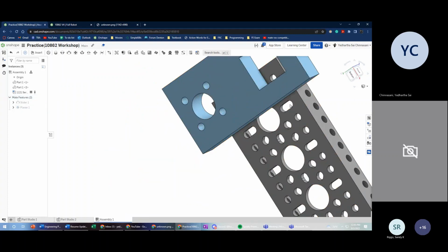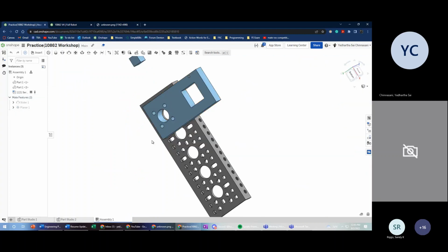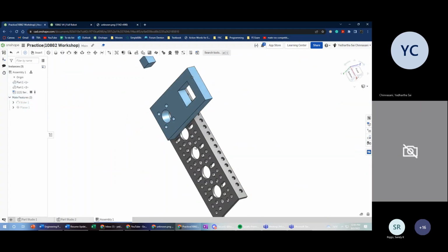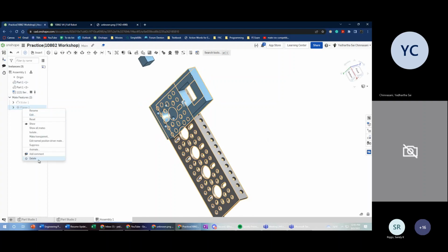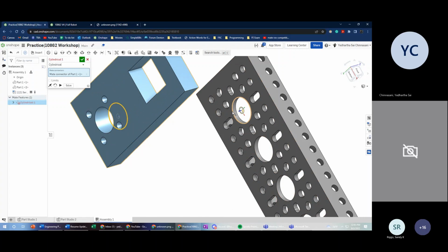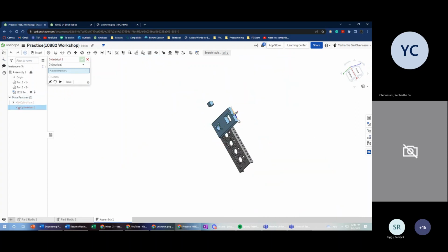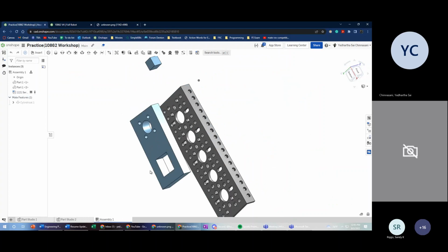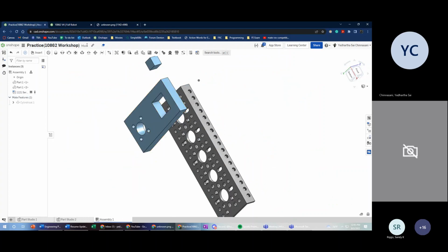It's a planar mate, and now the part can't move because we're on a slider mate and planar mate. And if you want to use an interaction between a slider mate and cylindrical mate, that's something that's a combination of a Revolute mate and slider mate, is what I was trying to say. So you press the same holes, and you are able to spin this way, and you're able to slide it out. These are the mates that you're going to use most of the time.